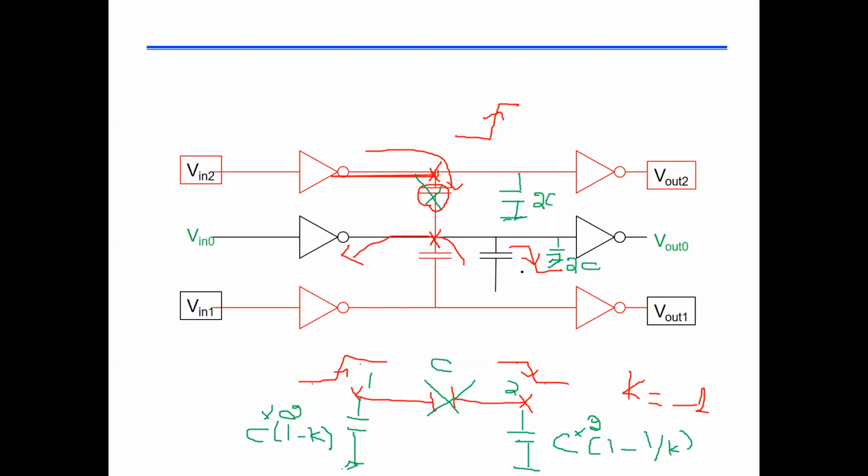Okay, so now I don't only see my wiring capacitor but also my coupling capacitor affects me by twice its amount, because I have a gain of -1, because the other person is opposing my signal and I'm also opposing his signal. I'm also affecting him by 2C. I'm also delaying him. Now the slope will be reduced a bit in both of us, but we're seeing double the capacitance.